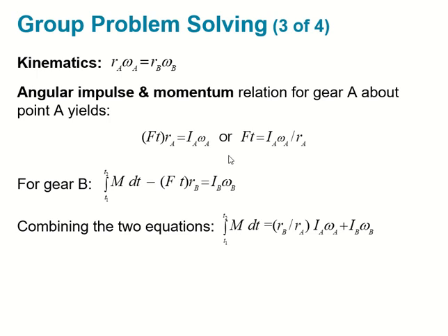So we go into the angular impulse and momentum relation, which is this. You start with the A here. We put in everything that we understand or is given here, which is your moment of inertia, the angular momentum with your angular velocity, multiplied by some distance away from that force making the gear rotate.